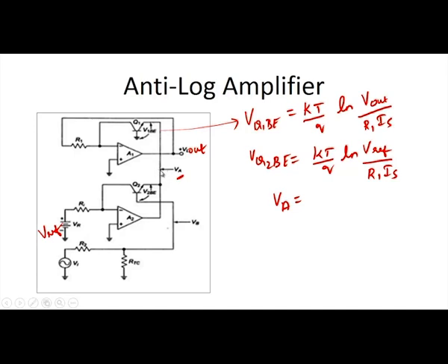If you want to write the VA equation, this is actually the reverse of the base emitter of Q1, because the base of Q1 is grounded here, and for the emitter terminal we have written the equation. Here for VA, it is not so, it is actually reversed for VQ1 BE.